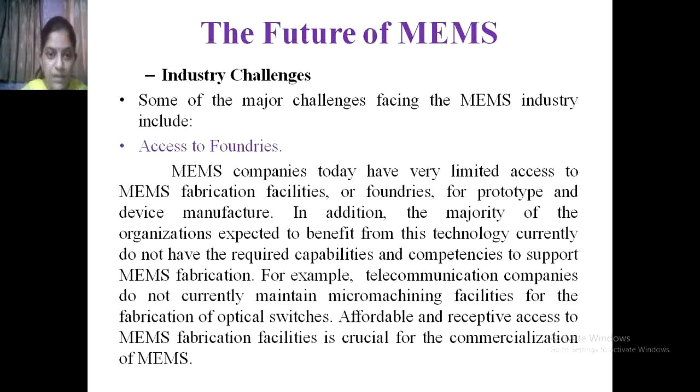In the history, as well as in the introduction of this chapter, we have seen that MEMS is nothing but the micro electro mechanical system. So whenever we are going to design any micro system, we have to take into consideration the scaling laws required for MEMS devices or systems. We have to design very small micro components, and over that, using bulk micro machining or surface micro machining, we have to fabricate the devices.